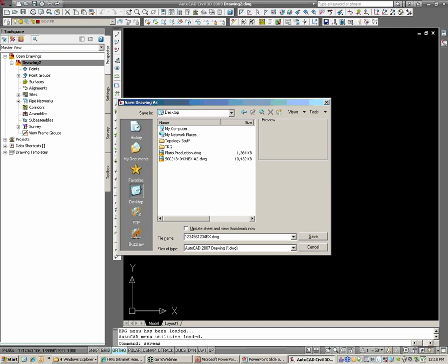Now, if you're in survey, that's your service group. Of course, you put an S in the front. That's our standard for the survey service group now. But if you were building base mapping and you're another group, like myself, I'm in land development, I would put an L in front of this if I'm building this land development base map. Just because it's existing conditions does not mean that survey owns it. If you built it, you own it.